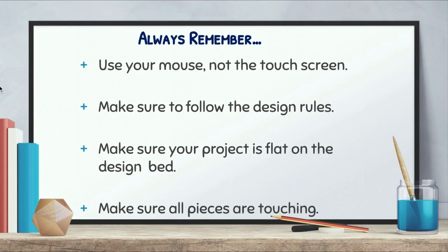Make sure your project is flat on the design bed. It's easy to accidentally raise your design above the Workplane in Tinkercad, and this can cause problems with printing. I always encourage students to check this before submitting any designs. Finally, any pieces that should be printed together need to be touching. Nothing should be floating in space.